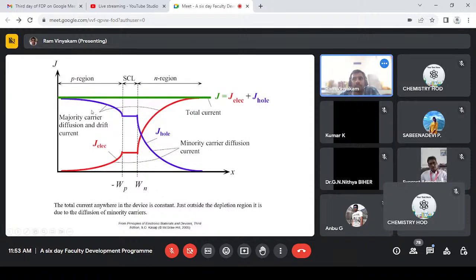So if I take a 3 micron silicon wafer that is already p-type, and I compensate by doping with n-type, if I dope along 1 micron by implanting, the width at the interface forms around 0.5 micron, and beyond 0.5 micron on either side, it will be the same as before. So the width of the depletion region is more important when you go for heterojunction devices.